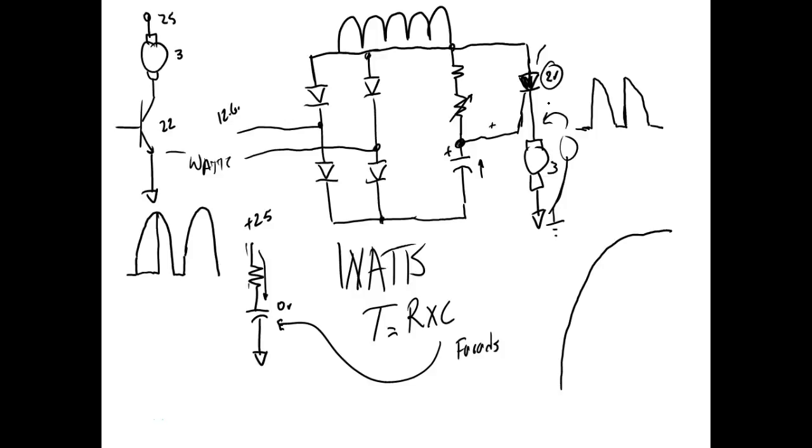So we don't run motors with transistors very often unless we do something called pulse width modulation, which is very, very popular now, where we switch the transistors off and on, which is pretty neat. So if you get out in big industry, and that's been around a while, you're going to see a lot of SCR drives. But somehow we've got to come up with a circuit that can get past 90 degrees.